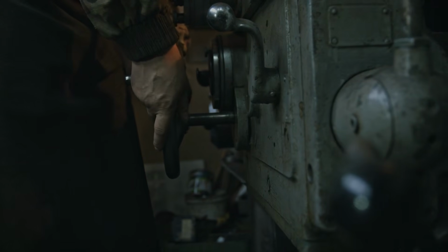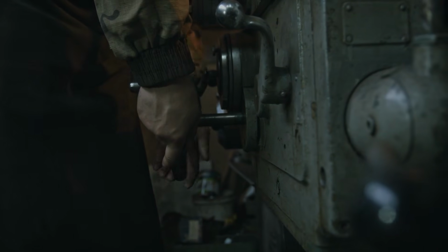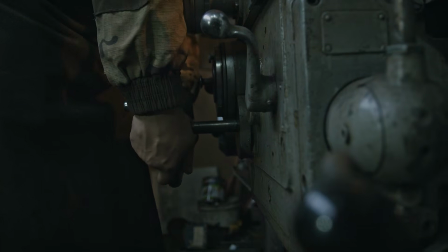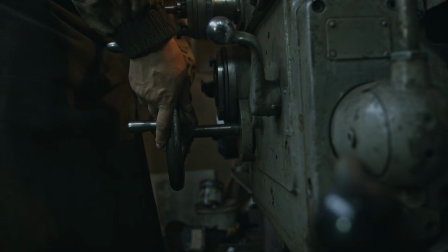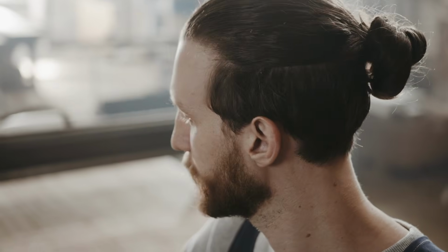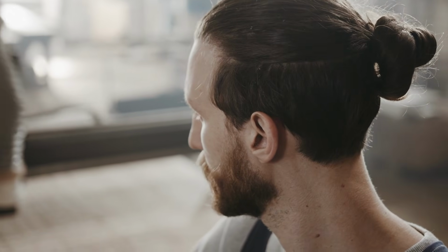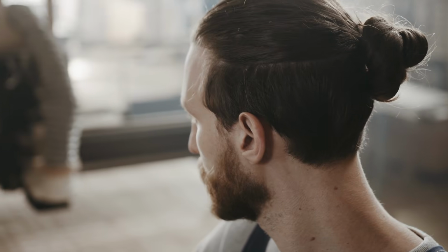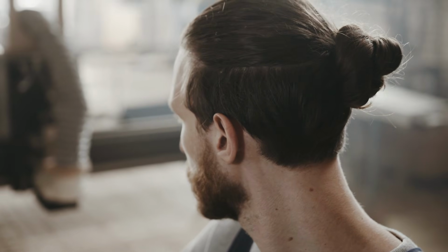This is shop talk. A part left the chuck at 2800 RPM and put a dent in the shop wall. The cause was one G code, G96. Programmer wrote G96 for the face. Tool walked towards centerline. Spindle climbed past chuck-rated RPM. Jaws let go. The fix was one line: G97 with a hard RPM.